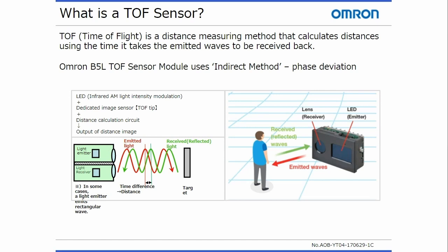There are two types of time-of-flight sensors, direct and indirect. Direct time-of-flight measures the undeviating time it takes the light to go from the emitter back to the receiver. It can be thought of as a stopwatch approach, where the sensor sends out a short pulse of light and measures the time until the echo hits the sensor. Direct time-of-flight sensors are best for using only a single or maybe a couple of points, sort of like a rangefinder. Indirect time-of-flight measures the phase shift between the emitted and the received light, where the phase shift is proportional to the distance. Indirect time-of-flight is best used for 3D imaging.